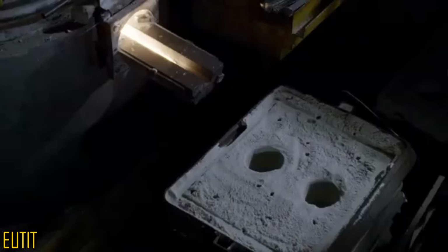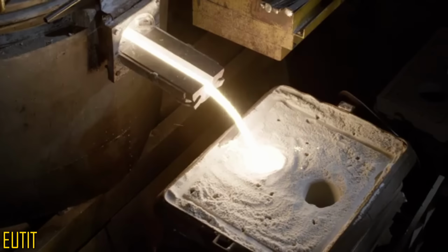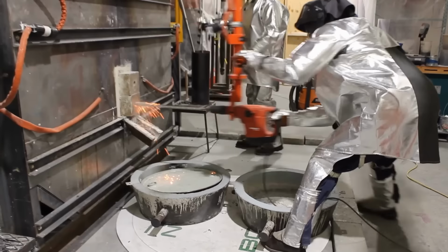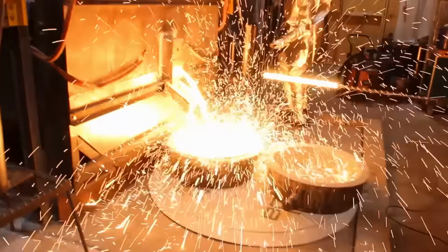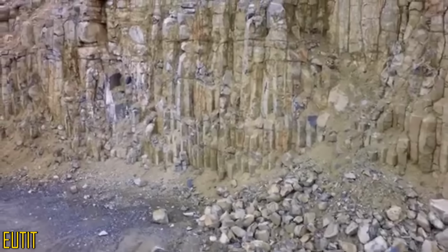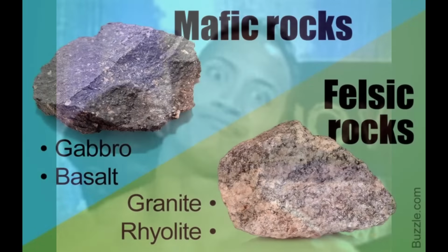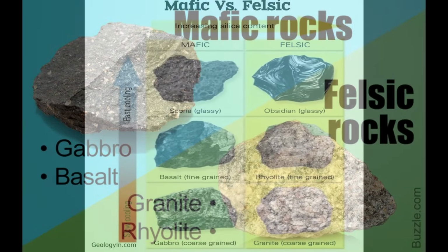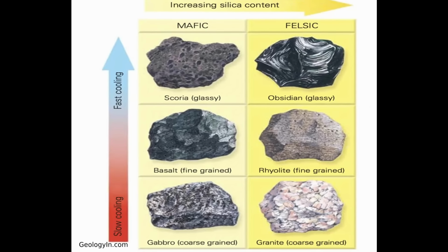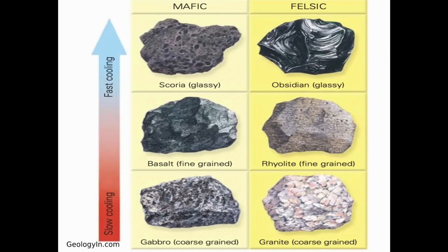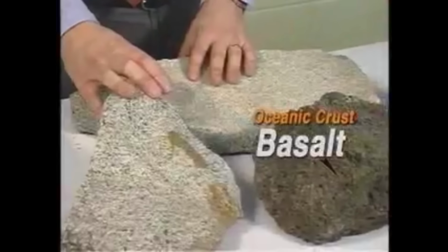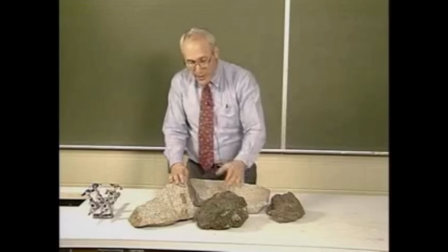This is cast basalt. To cast something simply means we melt it, then form it into whatever fun and useful shapes we want using a mold. We cast metals and glass all the time. Here we're doing it with rocks, specifically basalt rocks. Not all rocks are good for casting, owing to their differing chemistry and compositions. Basalt is mafic. It's fine-grained and relatively rich in magnesium and iron. Its minerals begin melting at relatively low temperatures, around 1200 degrees Celsius, and they all melt roughly at the same time, producing a fluid, homogeneous melt.